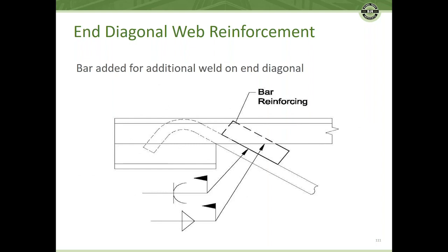There again, if you've got some problems getting some welds, this is a little detail that shows how to get a little more weld capacity on a rod member if you just need weld capacity.